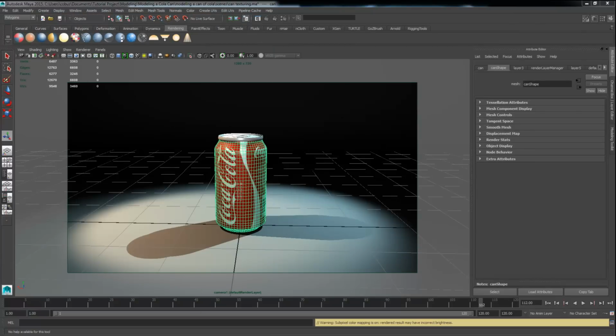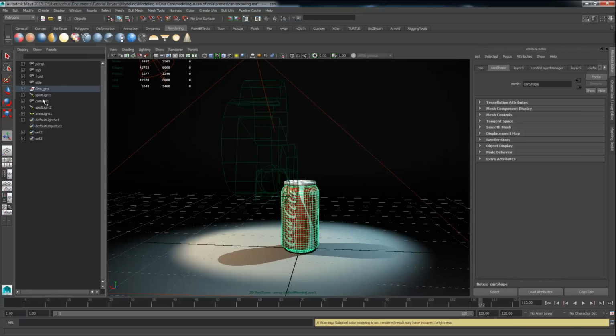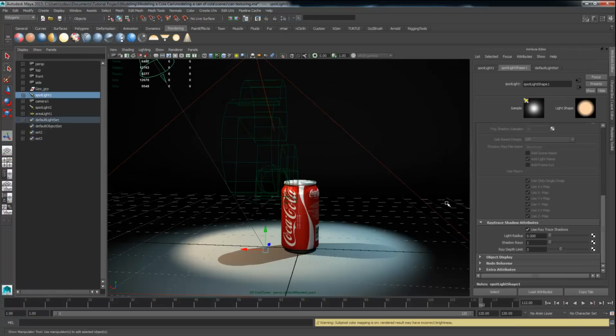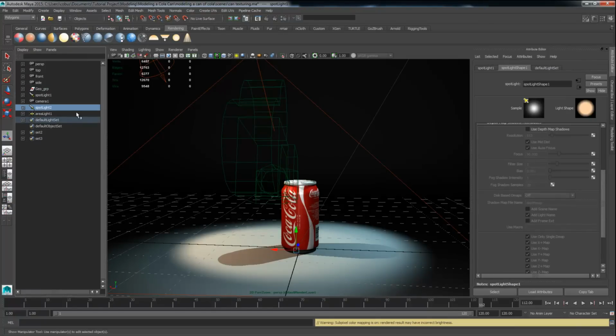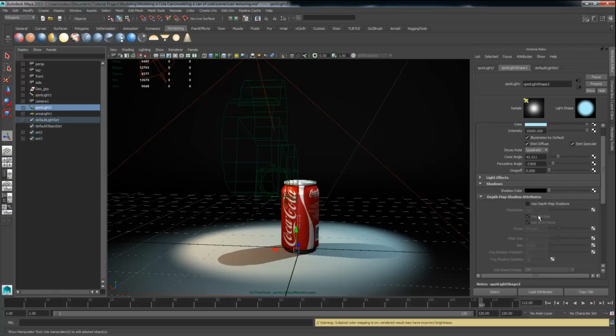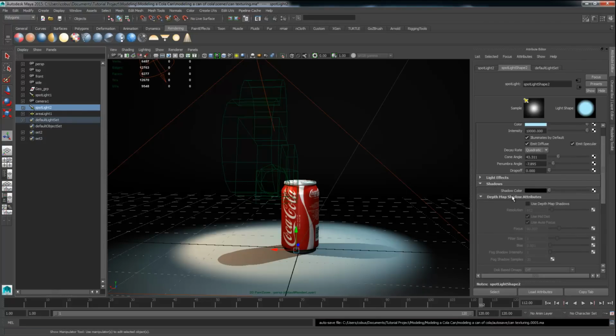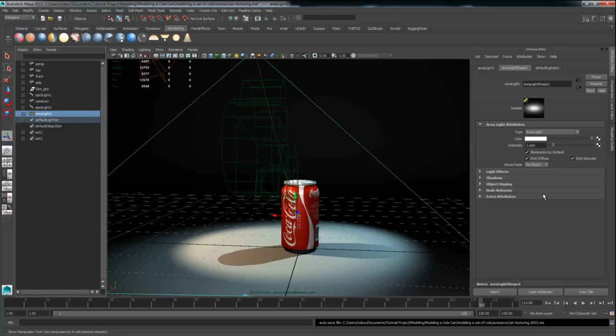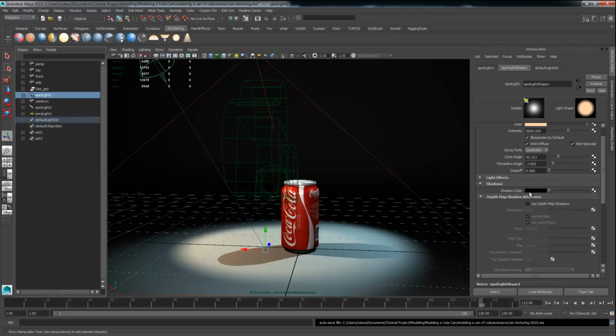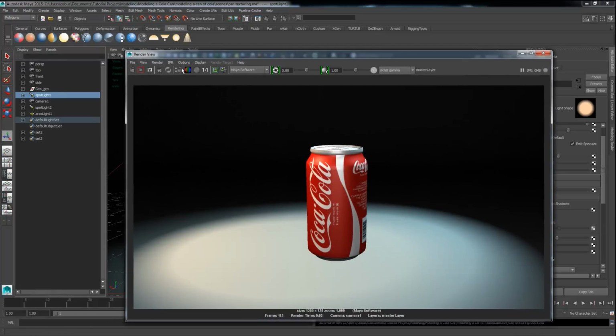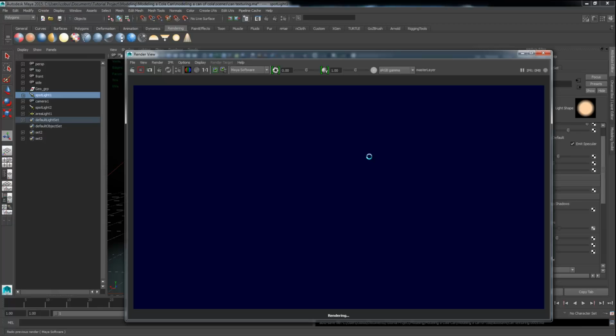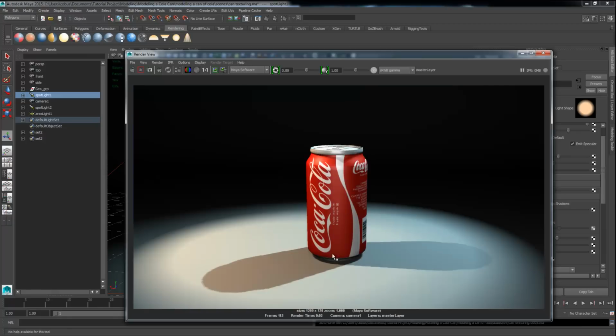and the reason for that is Maya software by default does not render out ray tracing shadows. You have to go and turn on the option for that. So I'm switching all the shadows from ray trace to use depth map shadows. I'm going to check the use depth map shadow options for each of the lights, and you can see the area light is also using depth map shadows.